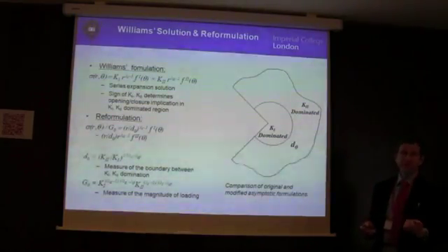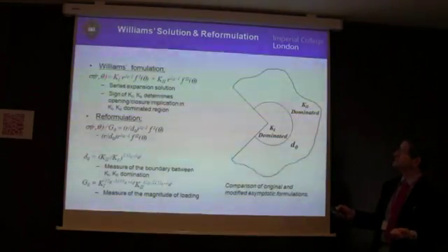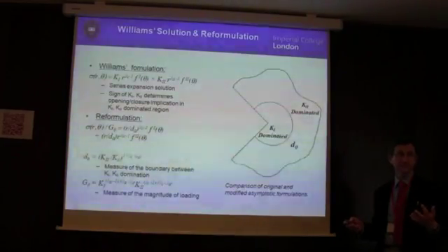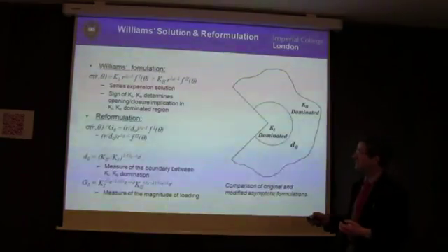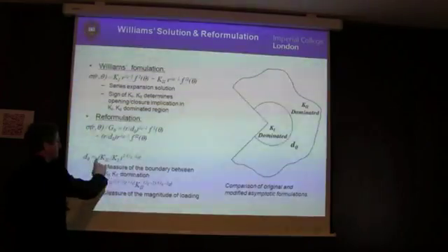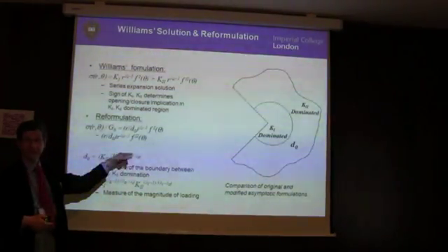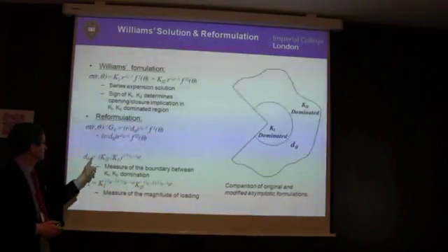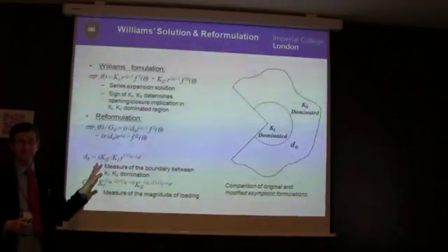Now, the clue, in my opinion, to the way that we look at this is we know that these stress intensity factors do not have the same dimensions. They're different. So we can bring out the length scale by defining this thing here. I hope that's big enough to read. So it's the ratio of K2 over K1 raised to some function of lambda. And the lambdas, don't forget, we know those from the Williams solution. So this d naught has got dimensions of length.